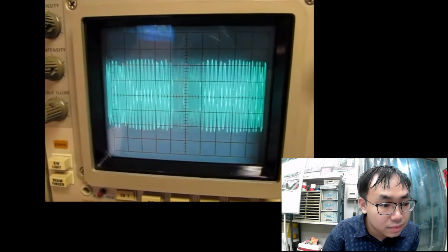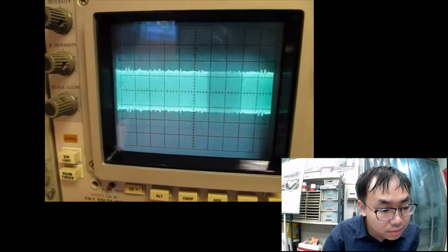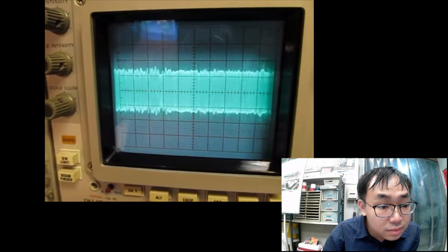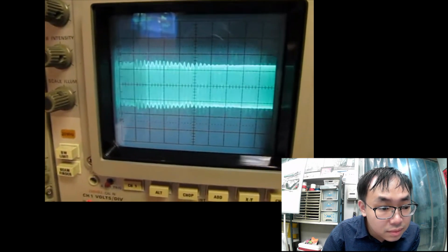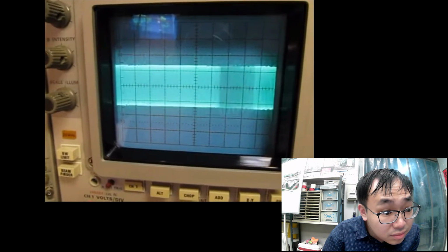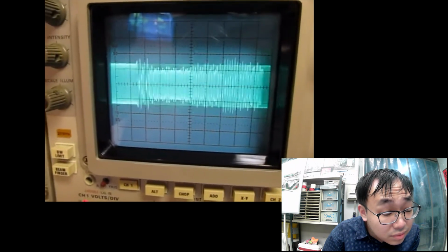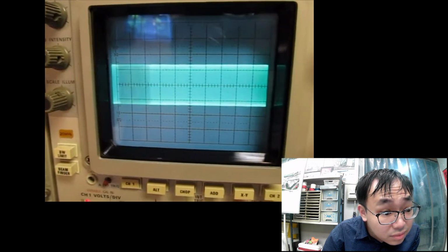We can make some measurements, or at least make sure we're not flat topping, and see if there are those little bright spots when I get really loud in the microphone, which means we're getting pretty darn close to 100% modulation, but you can still see that pretty easily.